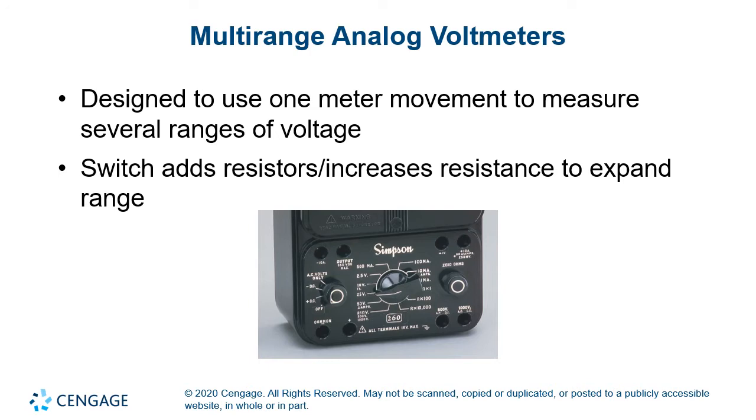So it turns out that what we have set up in pretty much all of our meters is a switch of some type, and it allows us to switch between different volt ranges, right? And it does that by increasing or decreasing the resistance. If we have a high resistance, we can have a high voltage range, and the current will be limited. On the other hand, if we have a lower range, we want it to still remain accurate, we need to use a smaller resistor.